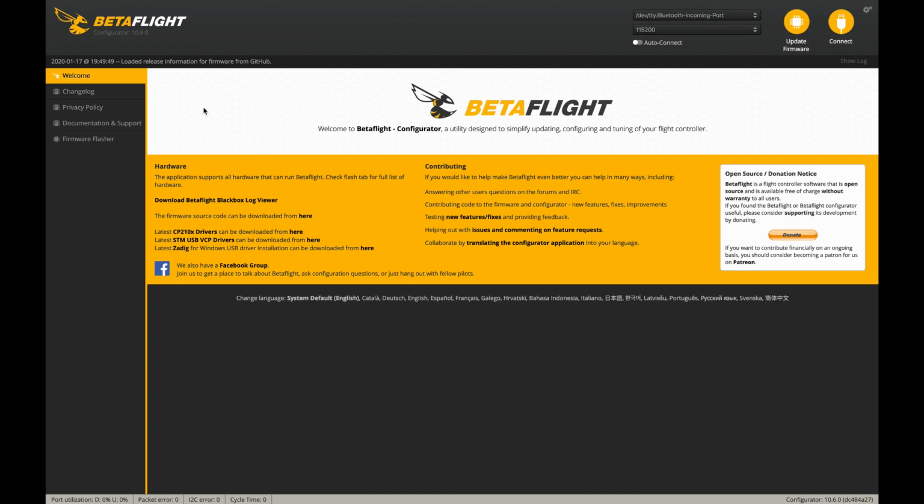And so here we are on the main page of Betaflight. There's tons of stuff. The very first thing you're going to notice on the front is it says latest CP210x drivers, STM USB VCP drivers. Those are drivers that you might need to actually get your quadcopter flight controller to talk to your computer.